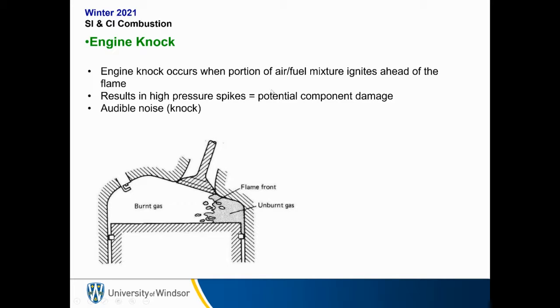This results in high pressure spikes, potential component damage, and also an audible noise, or knock, hence why it's called engine knock. We want to avoid engine knock at all costs because it's not only bad for efficiency, but it could also potentially damage your engine, slowly over time. Now, most modern engines are equipped with electronics to detect knocking, and they can retard the timing to avoid knocking occurring.